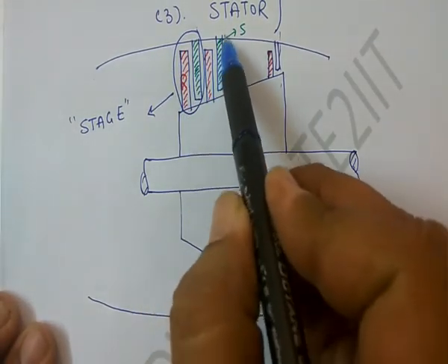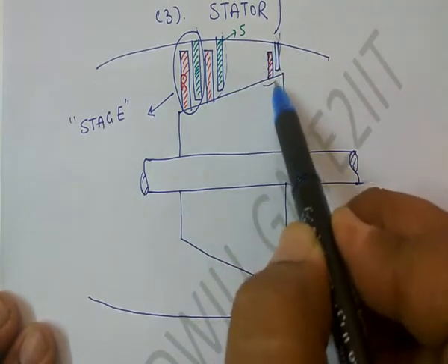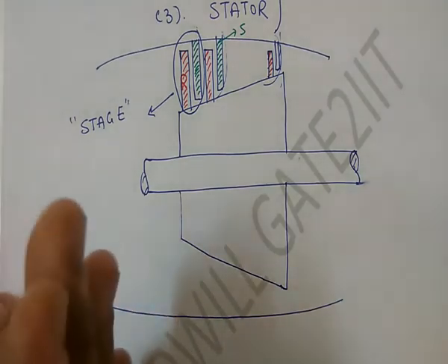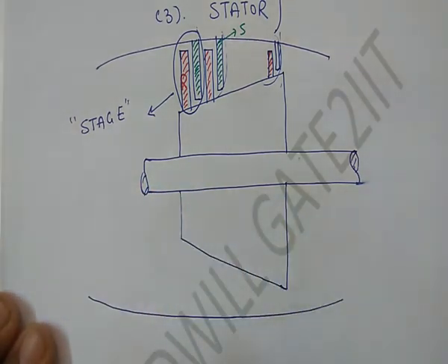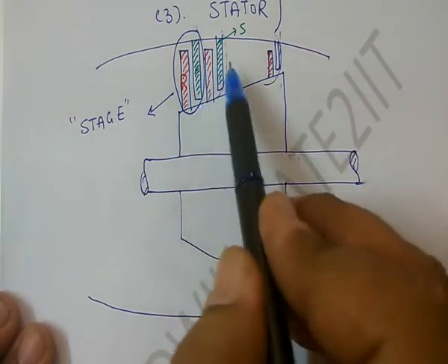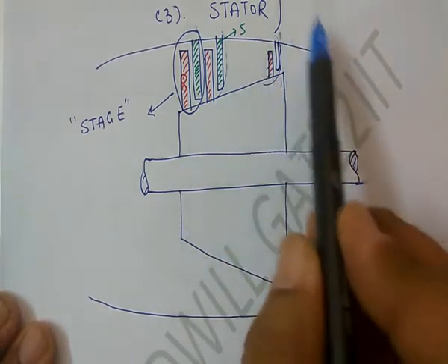Again, one set of rotor and stator blades, you have another stage, and so on, and this is the last stage. Alright, so in the process you have, let's say, 5, 8, 10 number of stages depending upon the requirement, what pressure you want in the outlet. So each stage will contribute something in the pressure rise. In the end you will get the overall effect.